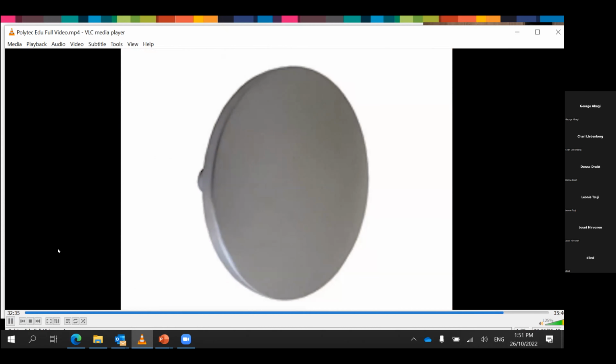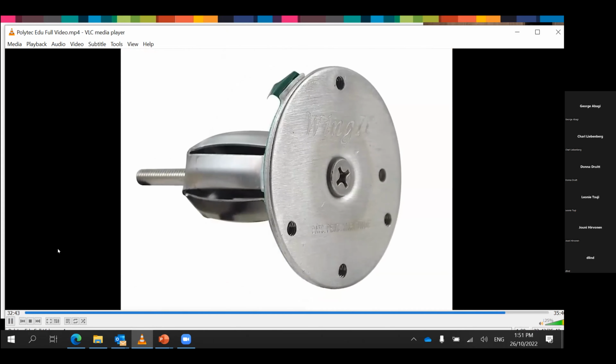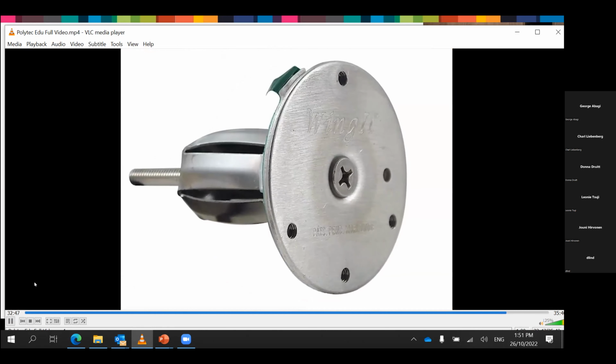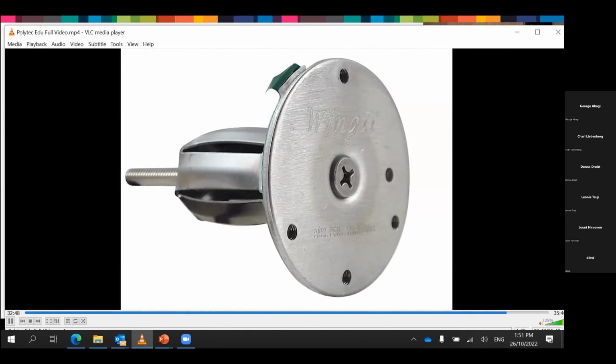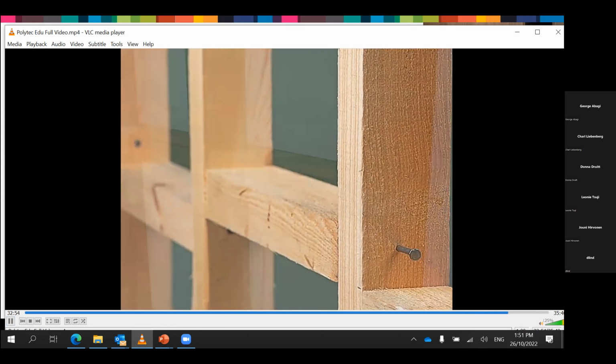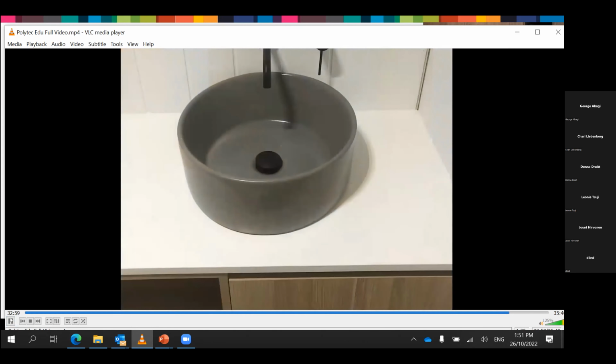Therefore, the grab rail is suggested to be fixed by bolting through the divisional panels using 6.4mm threaded rod and dress nuts, or proprietary plates such as bolt-through handrail fix plates. The same applies with toilet paper roll holders. When fixing to a cavity wall, an adequate structural member inside the cavity is required, such as additional nogging. Compact laminate can also be used.